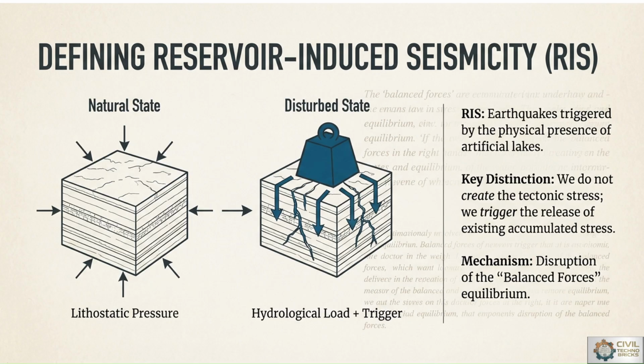When those stresses may damage the rock and it gets disturbed with reference to some water contact or some earthquake vibrations, that is hydrological load plus triggering activity, then reservoir induced seismicity comes in